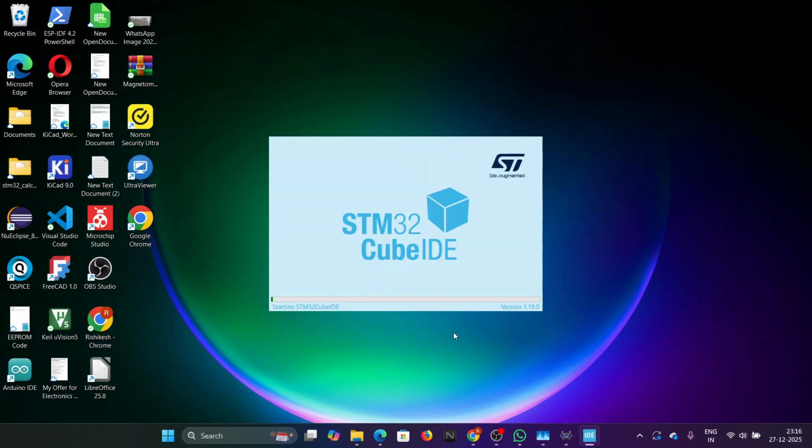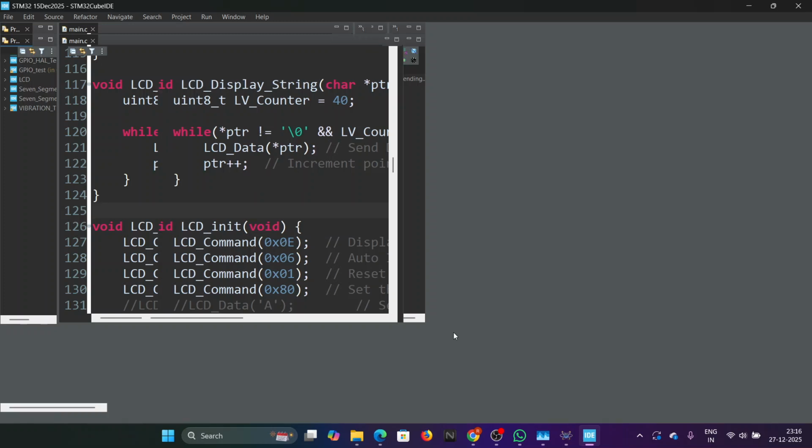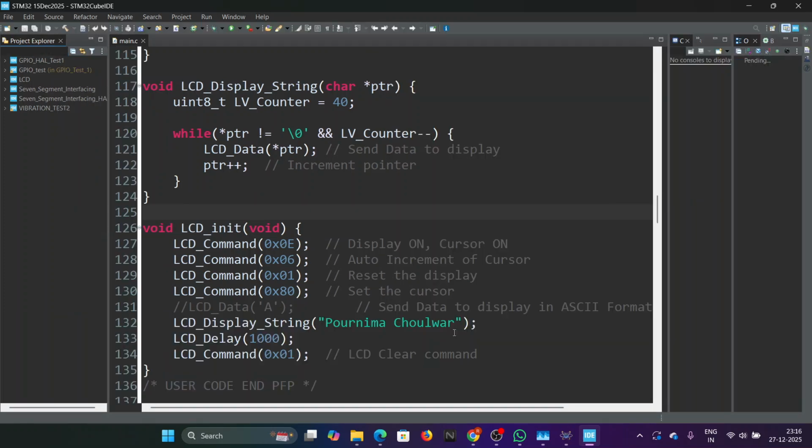You need to use both of them. I recommend that for most of your normal work you should use the internal clock, and if you need extremely high time precision, you need to use an external clock. PLL is for whatever clock frequency you need for your processor, you select it through the PLL while considering your actual clock source, like HSI or external clock sources.